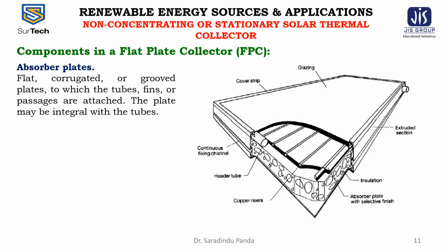Essentially, the typical selective surfaces consist of a thin upper layer which is highly absorbent to the short wave solar radiation but relatively transparent to the long wave thermal radiation, deposited on a surface that has a high reflectance and a low emittance for the long wave radiation.